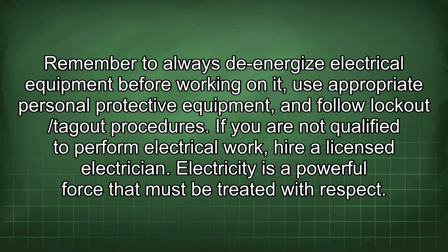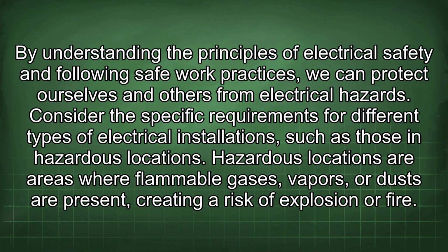Remember to always de-energize electrical equipment before working on it, use appropriate personal protective equipment, and follow lockout/tagout procedures. If you are not qualified to perform electrical work, hire a licensed electrician. Electricity is a powerful force that must be treated with respect. By understanding the principles of electrical safety and following safe work practices, we can protect ourselves and others from electrical hazards.